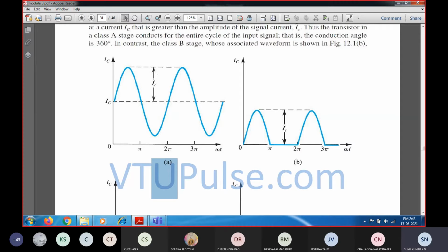So without any clipping of the circuit, clipping of the output happens. So that is about the Q point. Here the class A amplifier will just be operating at the Q point exactly at the center of the load line, so you can see there is going to be a full-length output without any clipping. The clipping of this output will not take place across any of this. So this is about the class A amplifier. The output signal varies over the full cycle of the input signal.